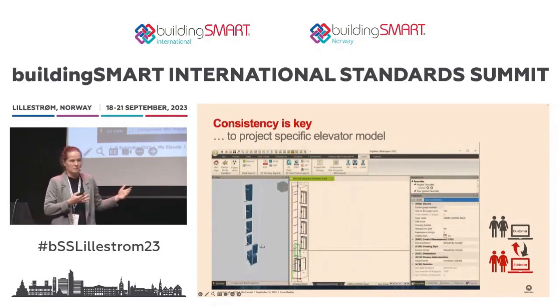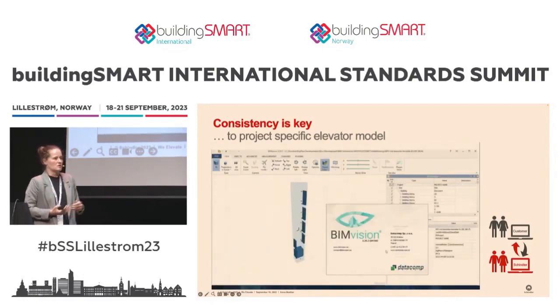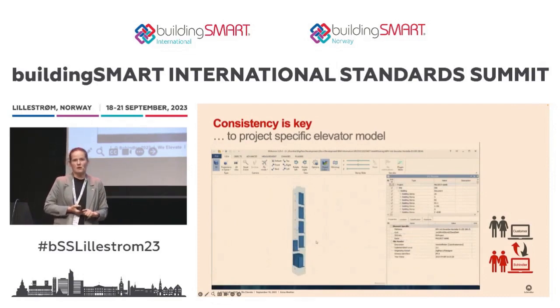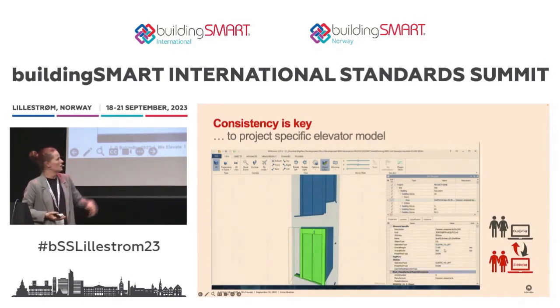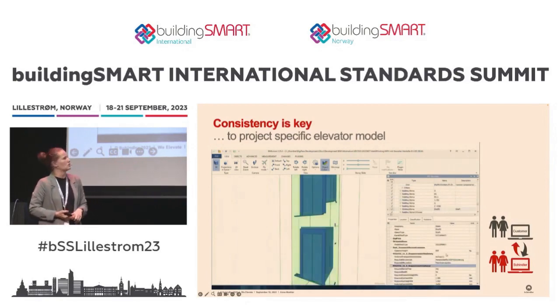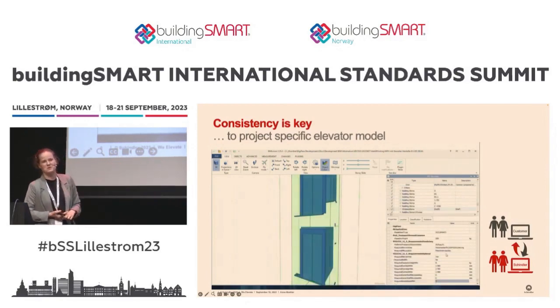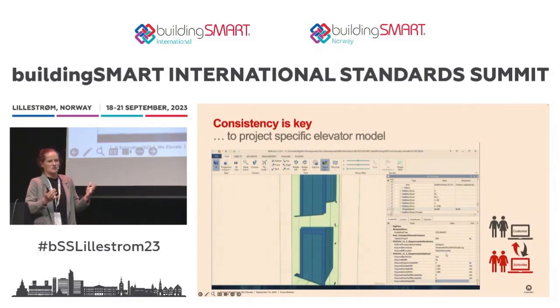So I think that possibility is already available. The main people currently asking for this data are on the architectural and planner side, asking for building certifications, for LEED, for example. And we already communicate via IFC with the stakeholders. So I think it would be a good solution to add some property sets in this direction, and so deliver a more complete IFC file for different use cases.